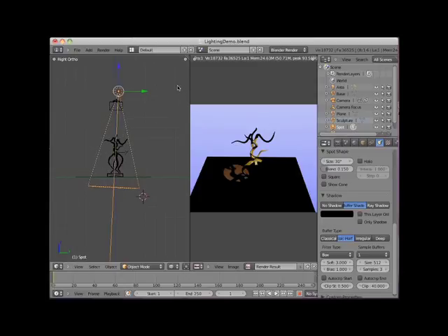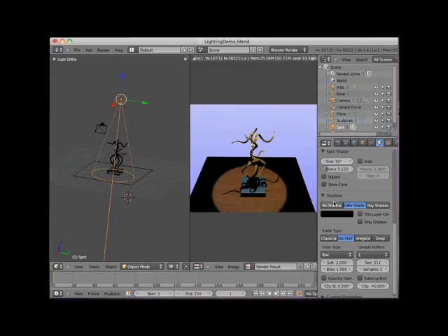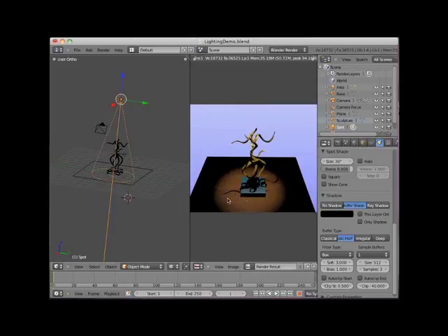The blend setting controls the softness of the beam. By default, it's set to 0.15, which results in a hard edge beam of light. Note in the 3D viewport the inner ring representation as I raise and lower the blend control. I'll set the blend at 0.9 and render the scene. The beam edge is now much softer.